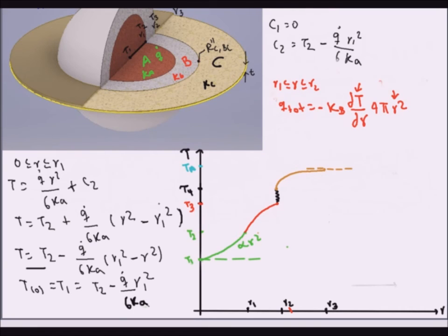And when you're sketching, you don't have to be exact. You just have to hit your boundary conditions. So please always remember to start with your boundary conditions. If it's a temperature or if it's a slope, label them before and make sure you understand them. And then once you do that, it's very easy to fill the gaps. Here we knew the starting point and the slope at the end point, so it just makes sense to connect them by realizing that the gradient has to decrease as you're increasing your radius.